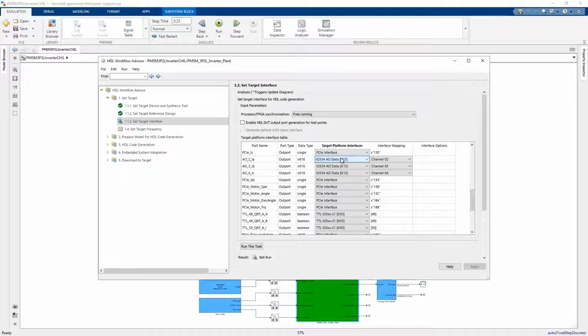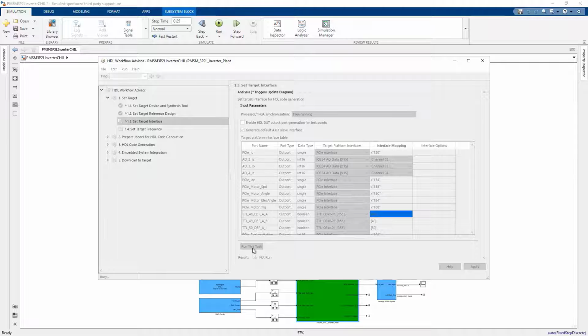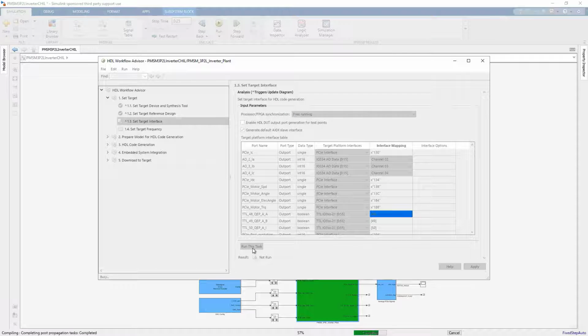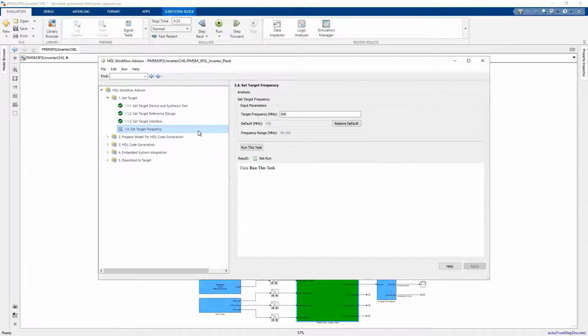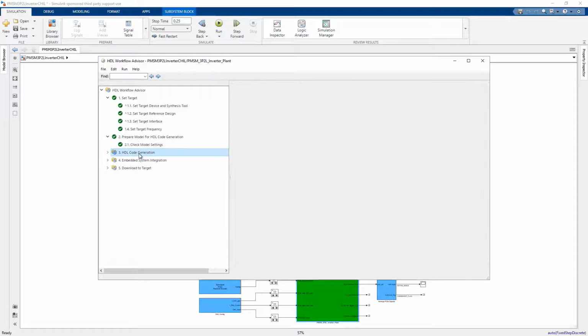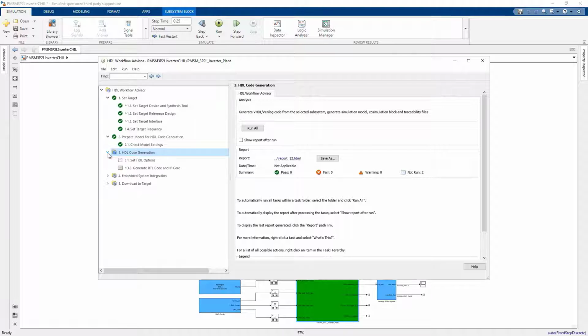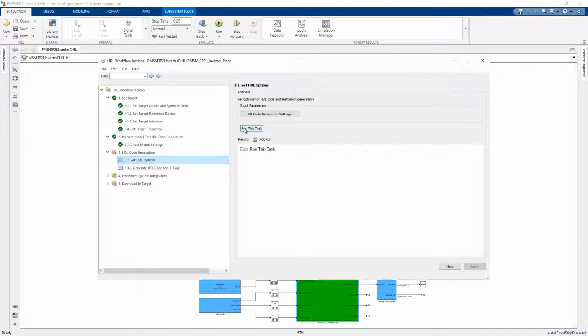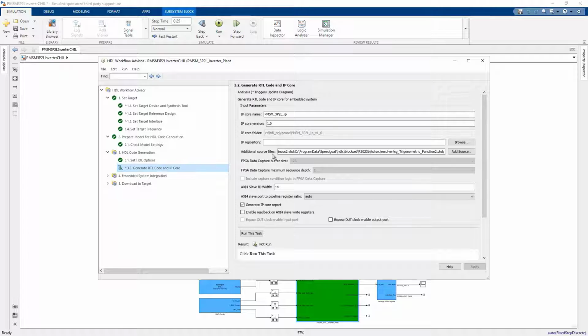In our example, we have the currents and the quadrature encoder outputs. The next step sets the clock frequency of the FPGA, here 200 MHz, corresponding to the 5 nanosecond capture of the PWM. We need to include the SpeedGoat source for the code modules.